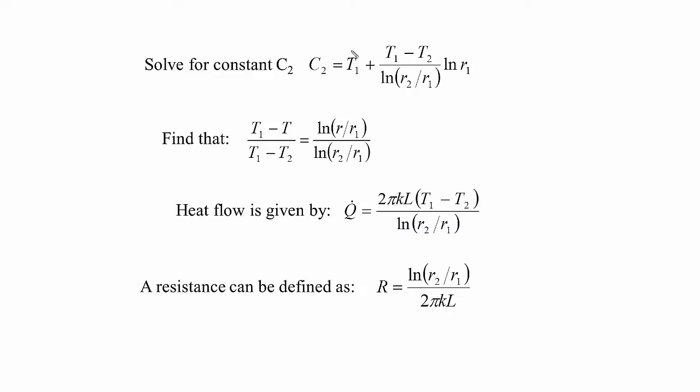So basically, solving for C1, we see that C1 is delta T over ln R2 over R1. We can solve for C2 pretty easily now because we already know what C1 is. We could solve this in terms of T2 or in terms of T1, and we chose T1 here. In both cases, we know what this relationship is, and we would have had, for example, T2 plus (T1 minus T2) ln R2 over R1 ln R2 if we had solved it in terms of T2.